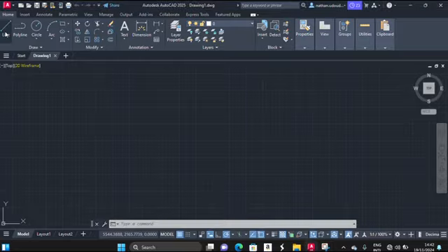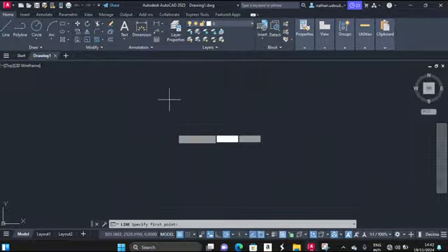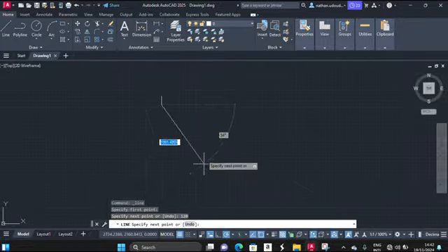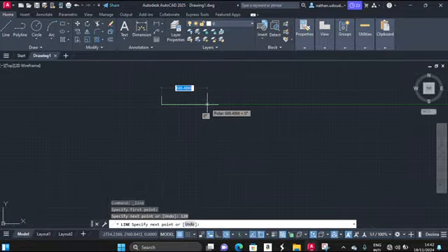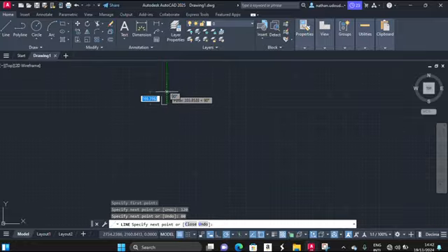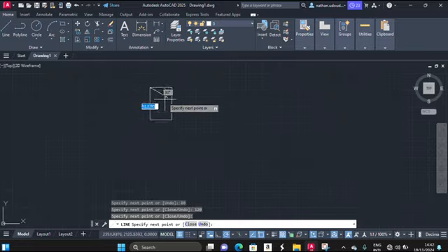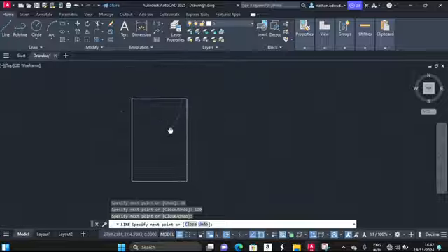So now you take a line command, after which you get the length of the external square thread, which is 120, 120, enter. Then the diameter is 80, 80, enter. And then back to 120, enter, and then back to 80. And zoom it up, and then escape.